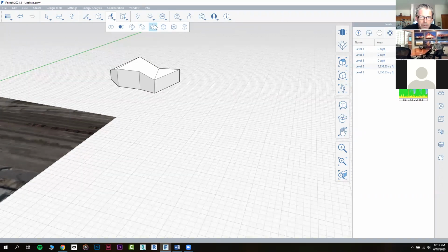But what I see happening most often with this tool at school is when I have a hard copy topography plan, and I can scan that and bring that in as a backdrop. This allows me to really quickly use a spline and trace out the contours, move them to the correct elevation, and then create really very accurate topography geometry from that. So that's what I want to walk through with this conceptually.